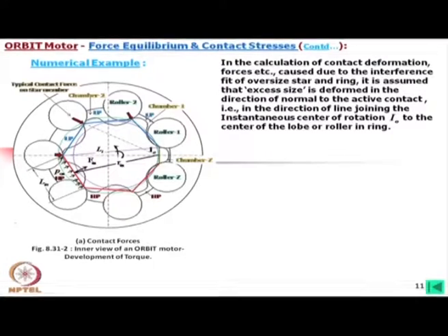Due to the pressure, it is giving a torque. Apart from that there is some unbalanced amount within the machine. That means, to hold the shaft at that particular position, you need some unbalanced torque. Although the magnitude may not be very high, this unbalanced torque is there. So, in the force analysis, such contact forces definitely give this unbalanced torque. So, while you are calculating, automatically this should also be taken care of.